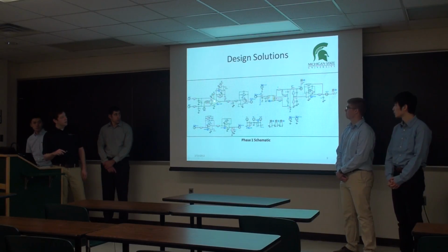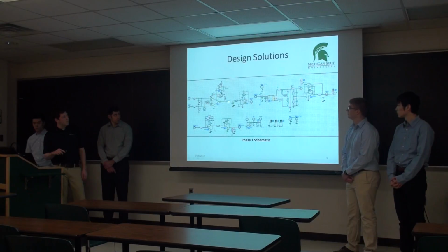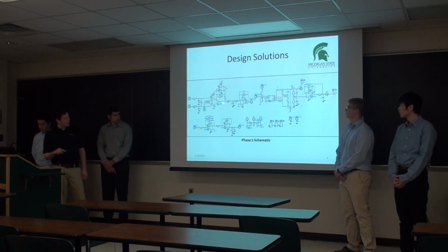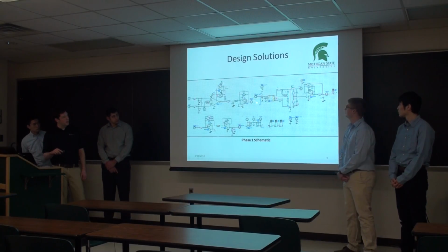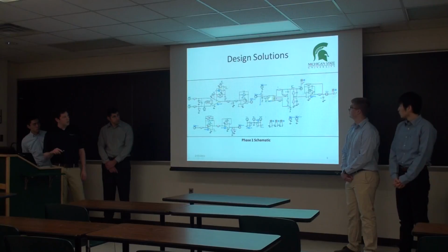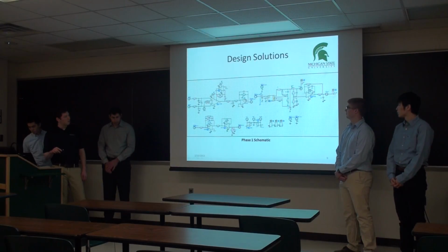This would be the servo loop that goes into the reference pin of the INA. Out here is the RC network that we might or might not use. This is the active filtering and gain that we have after the INA. This would be our power circuit. This is the TPS 62, whatever the number is.